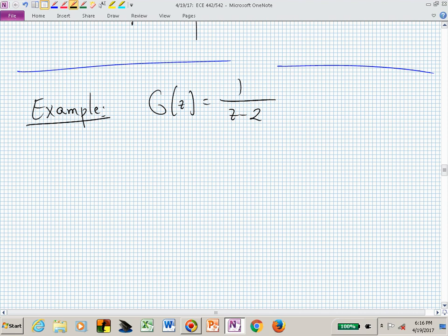But we would not have 0 steady state error due to a constant. We would have some offset. I put in a 4, and maybe it goes to 2.76. And maybe I don't want that. Maybe I want it to lock on. And how do I get it to lock on?